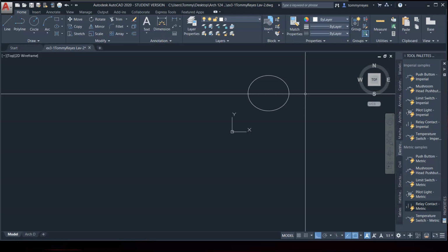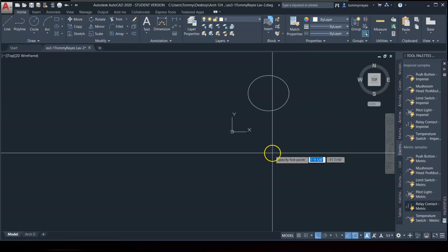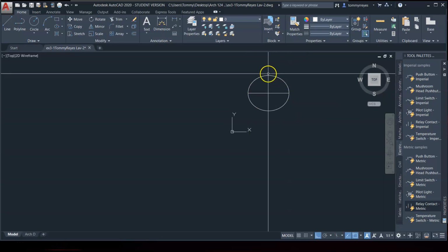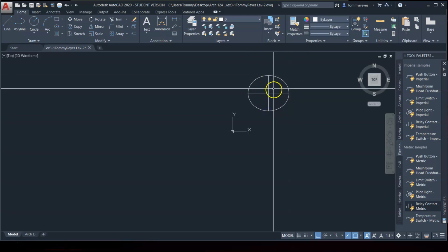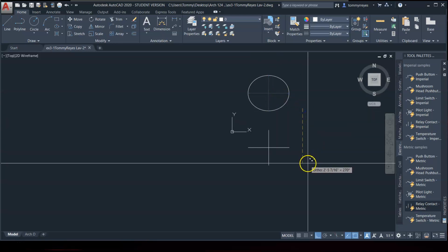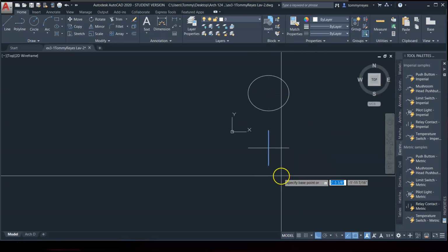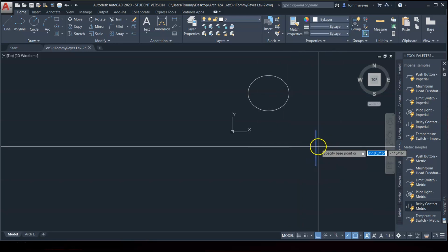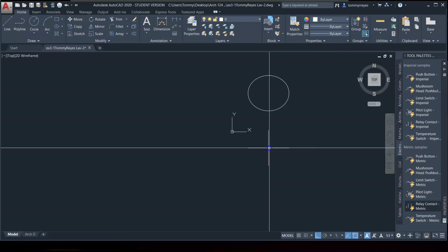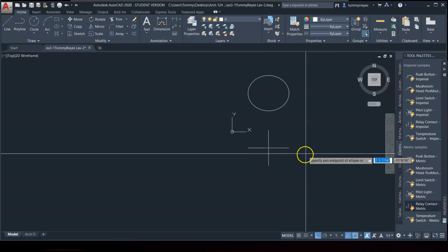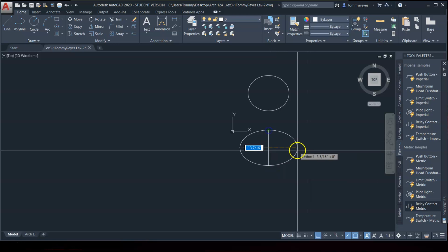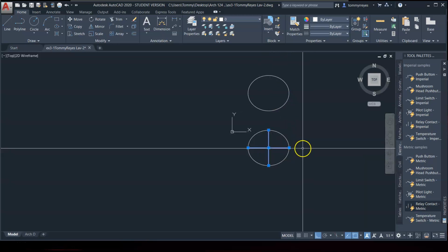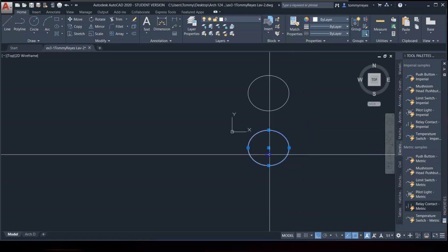If you ever come across an ellipse, and let's just say you knew the diameter from here to here and here to here, well, you can draw these lines first and separate, and then just move here to that midpoint, use the ellipse command, go from here to here, then to here, and it's the same thing. So delete the construction lines and you're good to go.